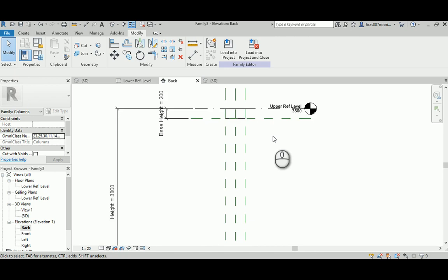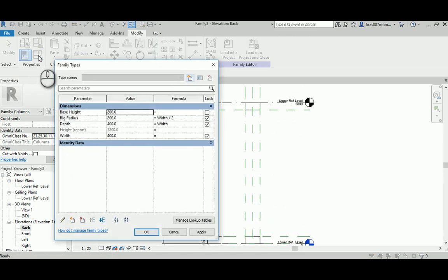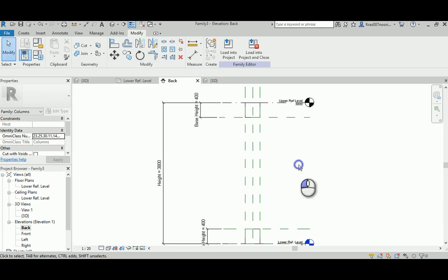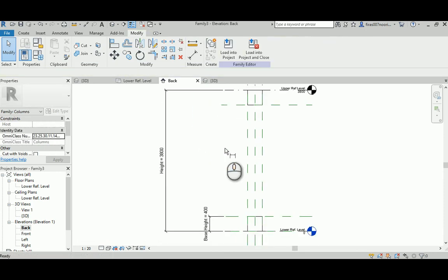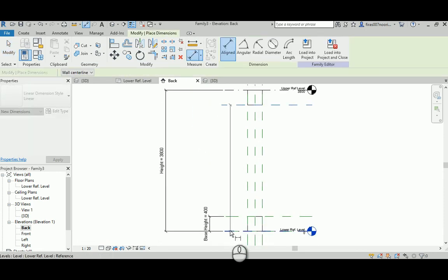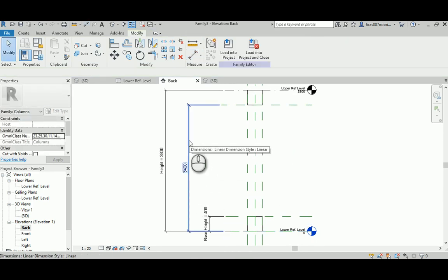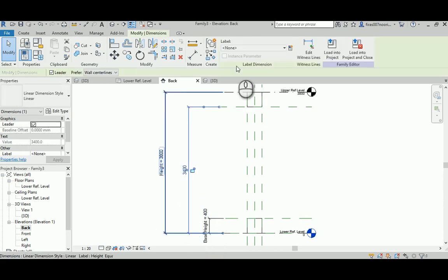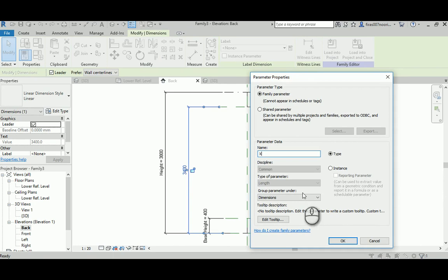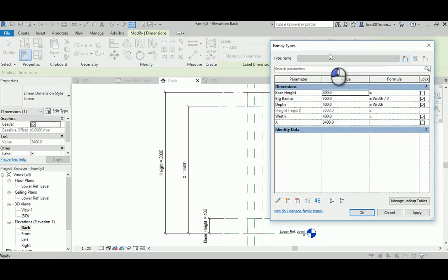So let's try to fix this issue, as I said. Again, if I go back to flex the base height into 400, hit apply, that's going to go really good. So select this guy, delete him, and I'm going to add a parameter from here to here, and this one actually controls the base height. If I select this guy and say it's X as a value, whatever it is, let's add a very basic formula for it.